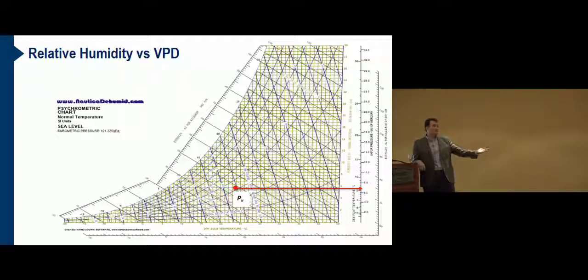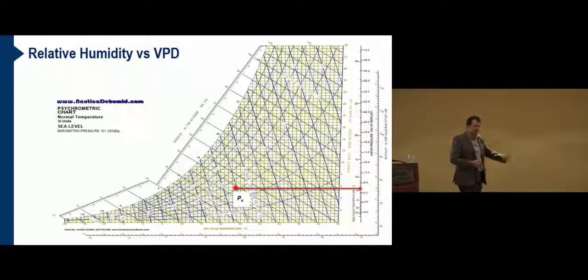In locations where the humidity is high and the temperature is high, we don't have so much capacity to cool using evaporative cooling systems, for example. So you can use a chart like this to log all your outside climatic data, hopefully historical data, some average temperatures and maybe humidities in your location. And if your data is falling into this region over here, that means you have high temperatures with high humidities. As you can see, you're so close to the saturation line, where you don't have a cooling capacity with fogging or fan-and-pad-based systems.